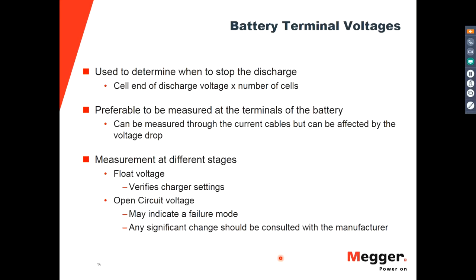Also, during the test or even before starting the test, you need to determine the voltages of the terminals of the battery. And we recommend doing this throughout the different stages that you see when running the test. So you get there, the charger is still connected, so the battery is floating. You want to measure the voltage, the floating voltage.